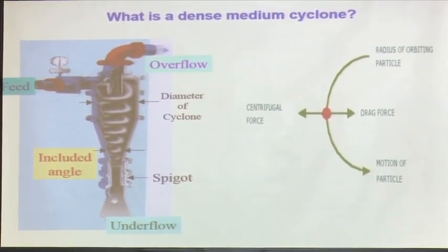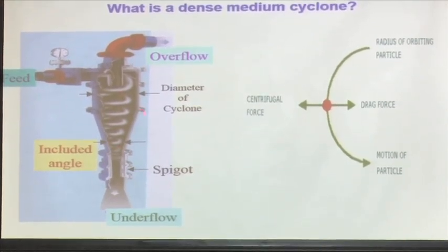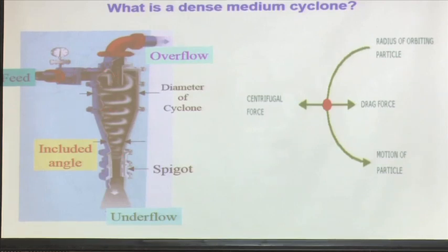So, what I am doing, I have introduced magnetite, and because of its fineness, it remains in suspension, because its residence time inside the vessel is more than my coal particles, because its mass is less. So, I am having an artificial increase in my suspension density, so that I can negate the size effect and I can have a float-sink effect.